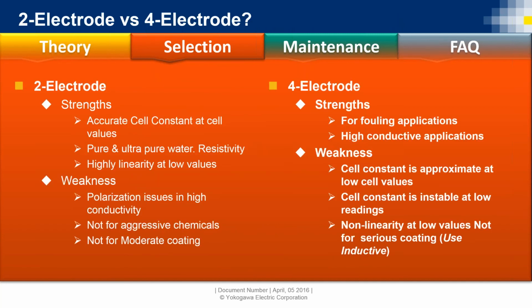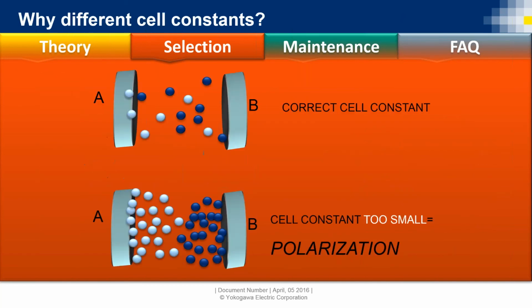Because when you go to extend the ranges of your sensor, you either have to A, change this multiplication factor, or you have to change the frequency output that the current alternates back and forth. And some vendors, Yokogawa is one of them, what we do is we change the frequency. So automatically on its own, the analyzer knows, okay, I get to this point and I have to change my frequency, so it increases how quickly it alternates that current to extend the range.